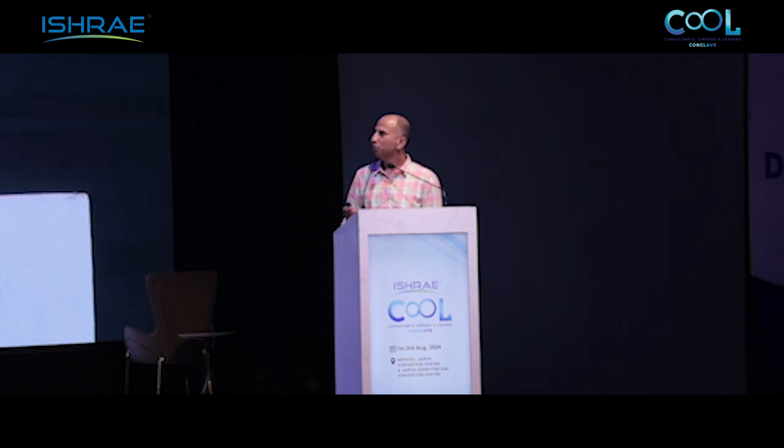Now, when we talk about choosing the right refrigerant, there are a lot of trade-offs, and we have to look at the environmental impacts, the ODP, GWP. We have to look at safety, which is paramount. What about the toxicity, flammability, the pressure rating, what are the chances of leakage or things like that. Then thermodynamic cycle efficiency. We all know that out of the overall life cycle emissions, 80% is attributed to the indirect emissions associated with the energy use. So efficiency is important. Cost, of course, is another consideration. Then system design and reliability.